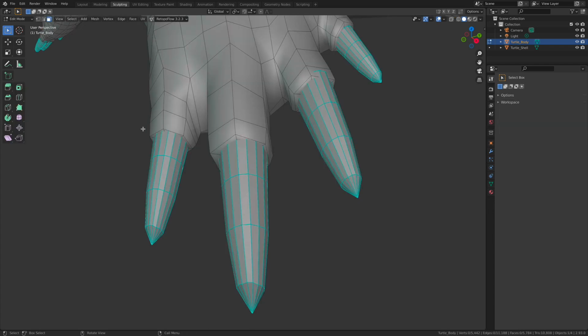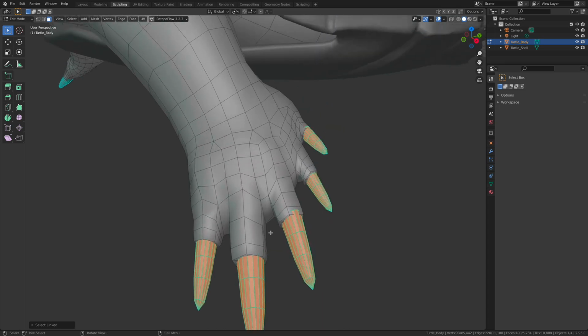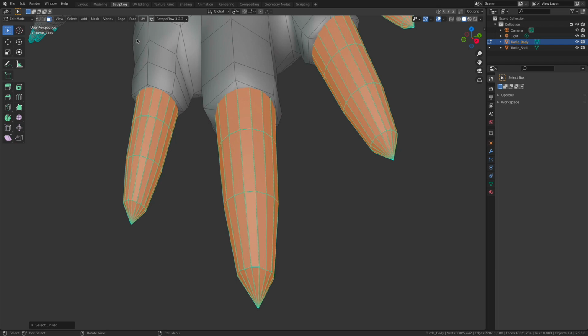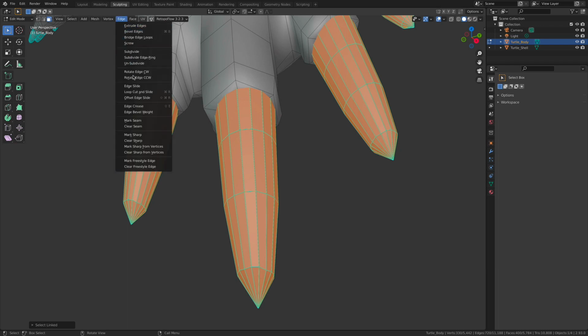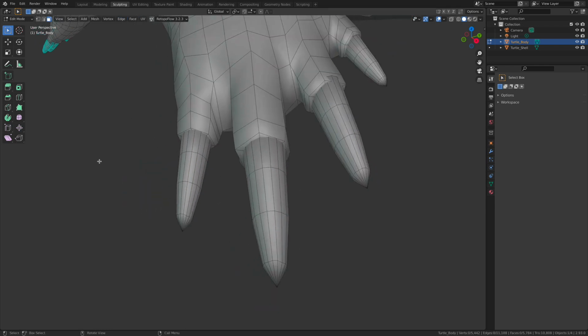And this is a great little Blender trick. I'm just going to go in, select all the nails. And naturally, I would do this on all of them, but I'm just going to do them on a handful just real quickly. And then we can fix the problem by going into the Edge pull-down menu, and we're going to do Clear Sharp. So inside of Blender, it's not hard and soft, it's sharp. That's how we do it. And with all that turned off, we clear all the sharp edges from that object.